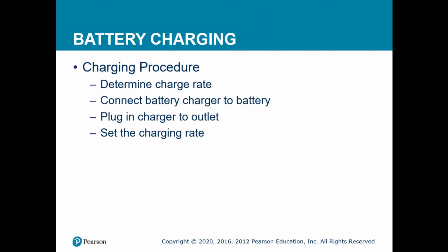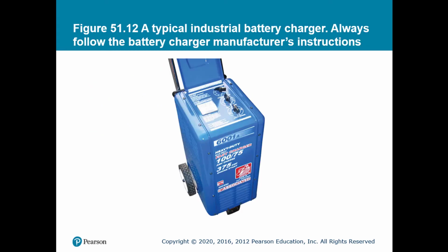As far as charging goes, you want to make sure that you're using the right charge rate. Essentially, that's the most important thing about battery charging. And I'm always going to say low and slow, but we don't always have that luxury. When you are charging a vehicle, you're going to have probably one of these shop chargers that wheel around. And in these, you can set both the actual charge rate itself, and you can also set a timer. That's what these dials are. So you want to make sure that whatever charge rate you choose, you set the timer as well.